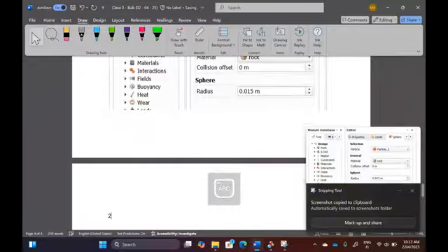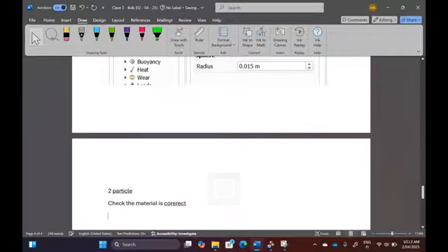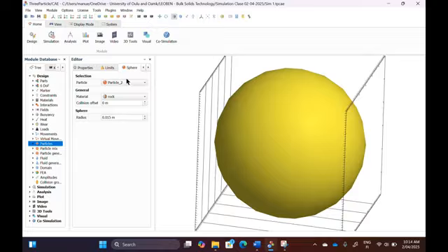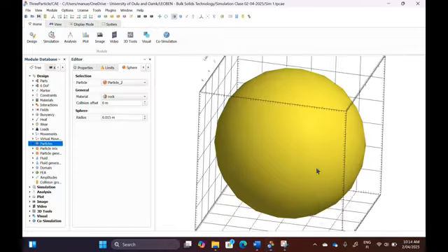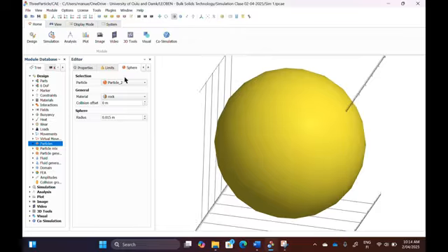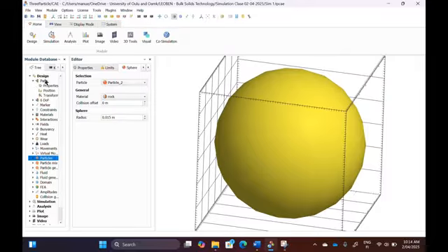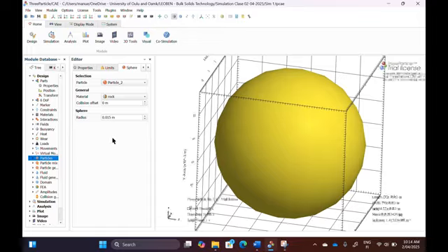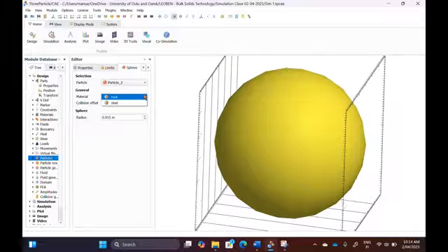So we have defined our first things. If we come back to materials, it should be good by now. Actually, we should be able to simulate it, but nothing will happen because we don't have the source yet, we don't have the part yet. What we need is at least 2 parts, and I will explain why 2 again. At first, we need a ground, where the particles should be set on, so something like a floor, but not a box. Just a simple plane is enough for us, okay?